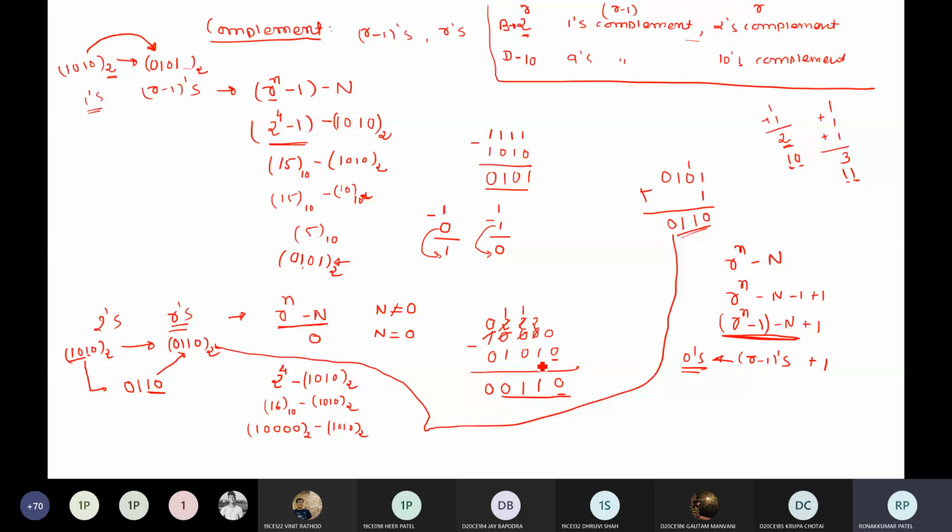Now the first 1 will be there. So here there will be 0 and it will borrow from someone. When it borrows, the number that comes here will be your radix. And when you subtract it, 2 minus 1, you will always get 1 for binary. So these last digits will not change, they will come as it is. But now for the rest of the digits, these two ahead, what are they subtracted from? From 1. Both are subtracted from 1.